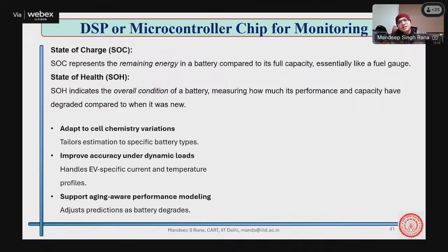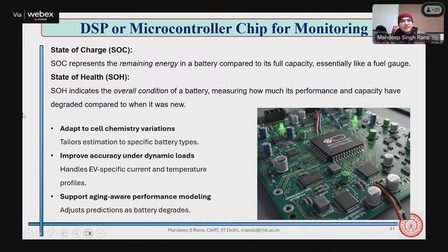These high-end processors which are sitting somewhere else, they would do the SOC and SOH sort of working. And it depends on various cell chemistry, various cell parameters to do that. But the good part is this AFE usually does not depend on the cell chemistry. So that hardware card remains the same. The higher end decisions which were being done in the high-end processor, which was responsible for the BMS, those things will change based on the chemistry, based on the pack size.